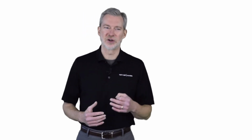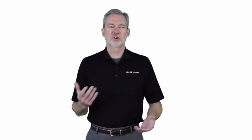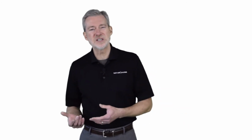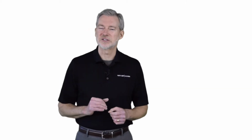As we noted in our first snippet, while robotic systems can repeat the gun path, speed, angle, distance to the part, flow rate, and total volume of sealer dispensed on every cycle, they can't compensate for the viscosity variations resulting from changes in ambient temperature that occur from morning to evening or season to season. As we see here, temperature-based viscosity variations directly affect the shape of the bead or fan pattern being dispensed.